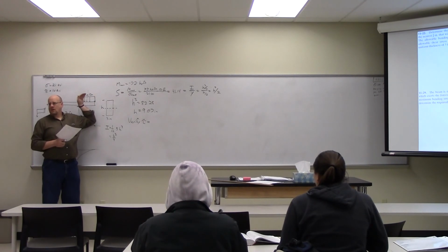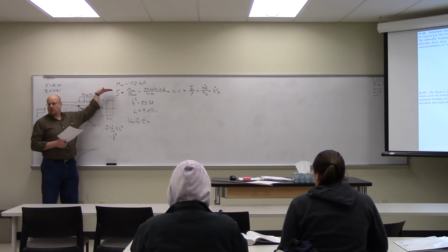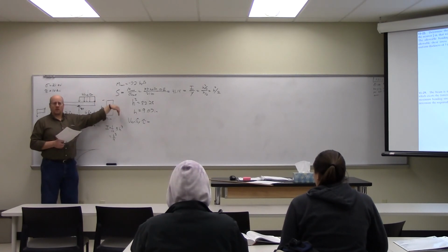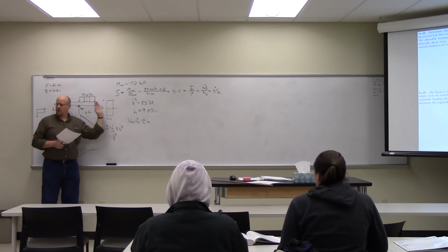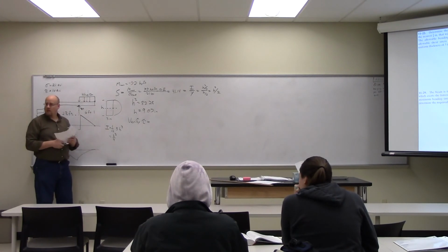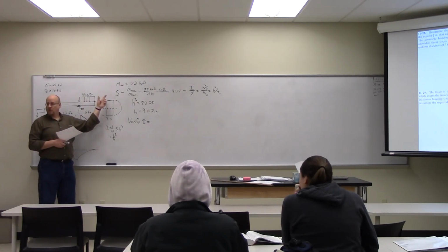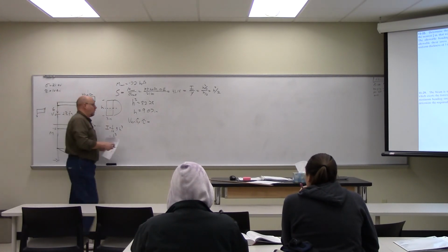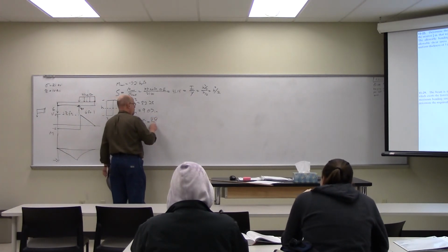So the shear stress kind of ramps up in the wide flange so that in the web, the shear stress distribution is not varying very greatly, right? It's not really a full parabola, it's just kind of a parabola on a square, you know what I'm talking about? Here, in this case, I'm getting a full parabola, because I don't have flanges at the top to offset my starting point for my shear stress. So I can't use that approximation here. I have to go back and use tau is equal to VQ over IT.